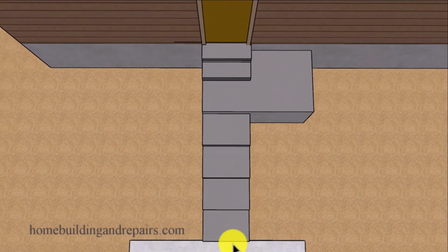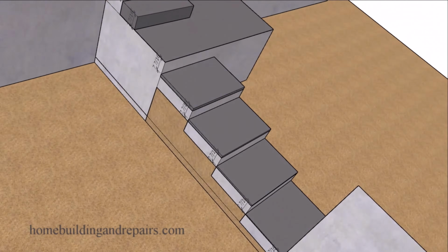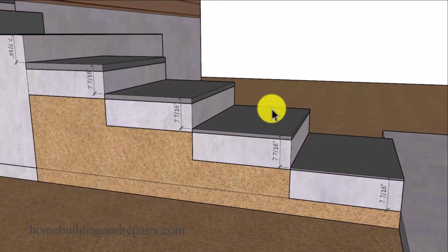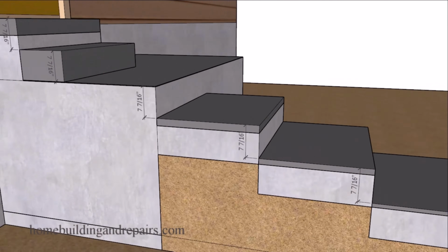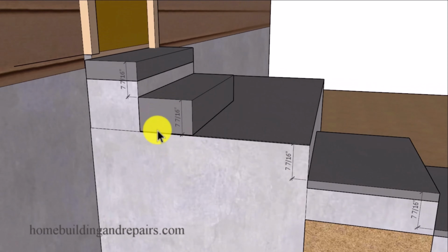So we're going to have 2 separate stairways with 2 different tread depths, 12 inches up here, 2 foot down here. And to accomplish this without removing the stairway, you're going to need to add a specific amount of material to the top of each one of the steps, and then build another step and then add some material to this one.